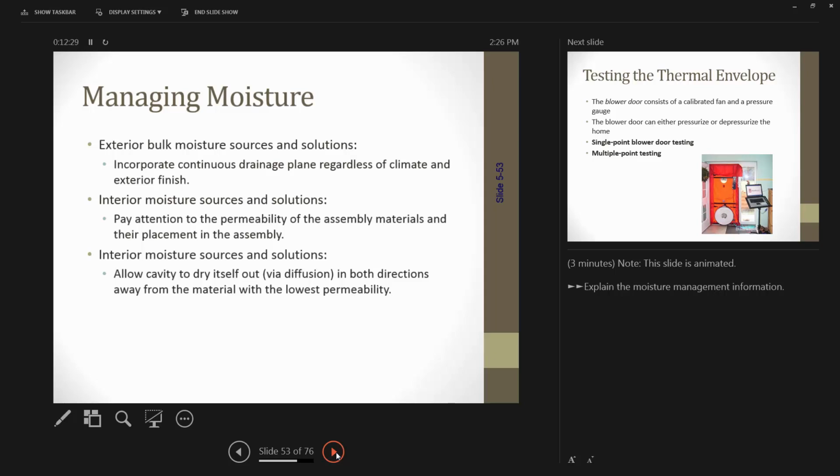We've got higher relative humidity inside and lower relative humidity outside. So not only are we losing our heat and helping to drive that conduction and convective airflow, but we've also got the vapor drive going from high humidity to low humidity. So we have to stop it on the inside of the wall. We try to stop that air from going into the wall cavity.